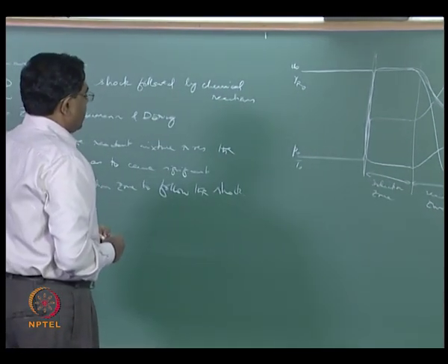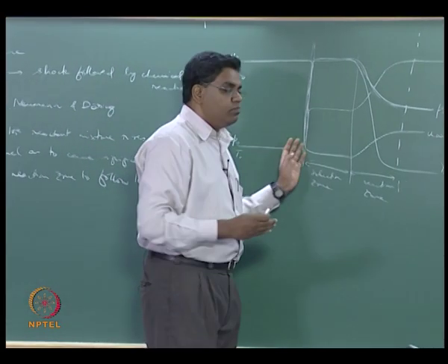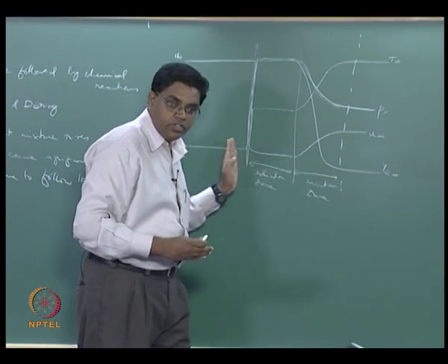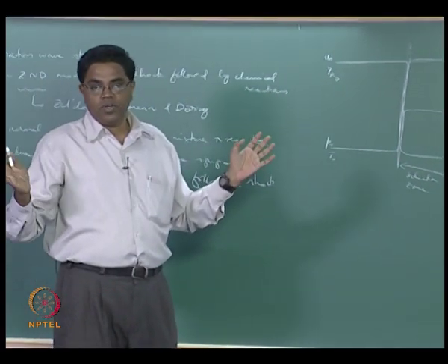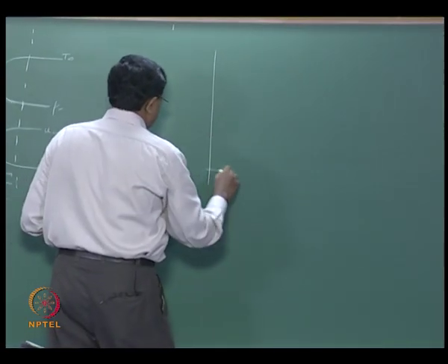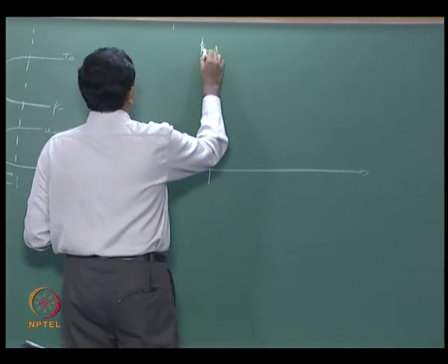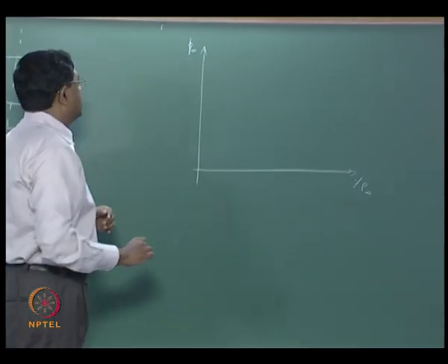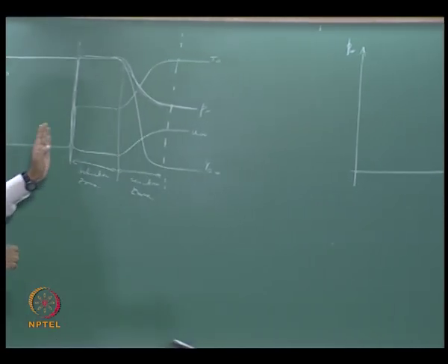So you begin to understand these kinds of things. So can we now think about how the state of the gases move through the reaction, so the detonation wave thickness within a Rankine-Hugoniot framework, right. So if I want to now do that, let me then plot my Hugoniot plot where you have P infinity and then 1 over rho infinity is what is classically plotted, but I am going to actually track the state of the system before it reaches P infinity.